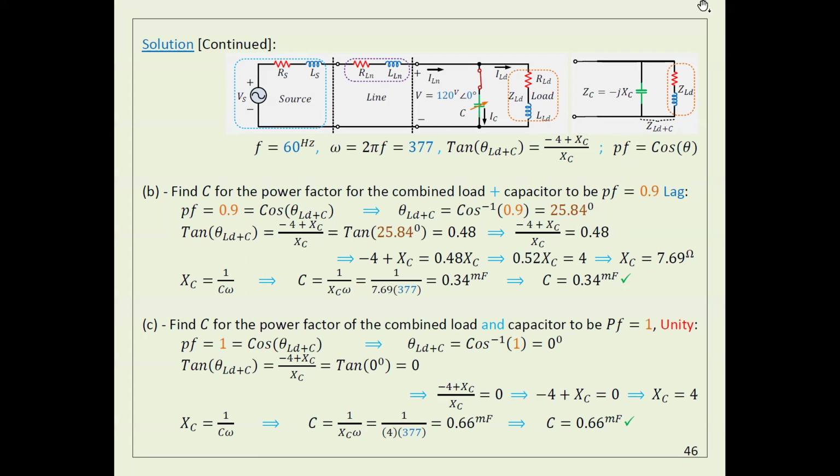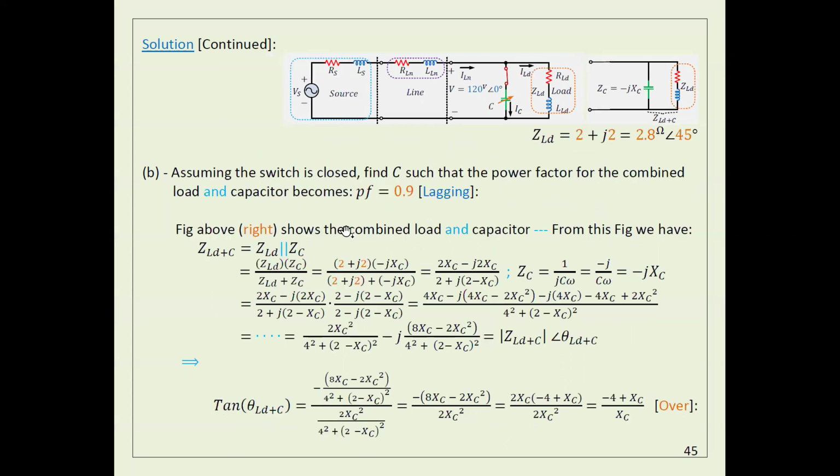So that's why I need to give you another piece of information. Here I told you it's given in the question: I want the power factor to be 0.9 and lagging. Lagging means the angle you calculate, take it as is, don't change it. It has to be positive.